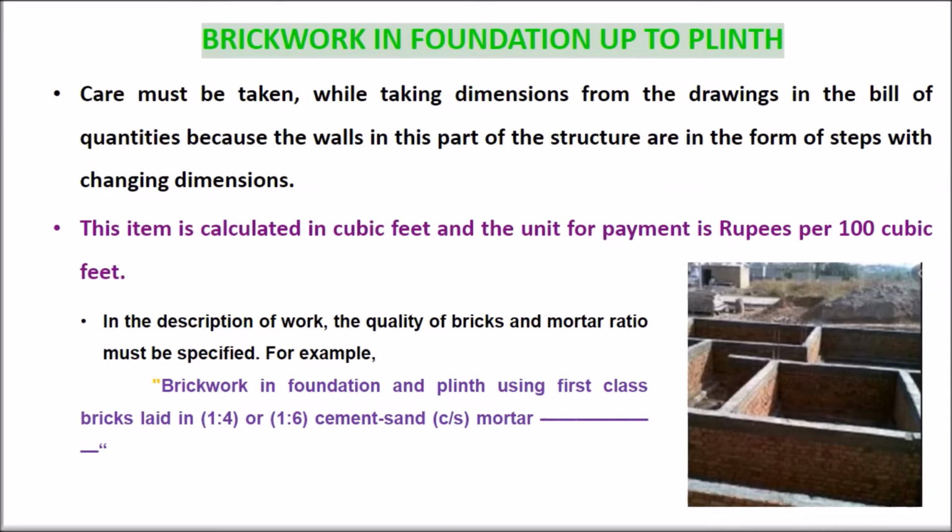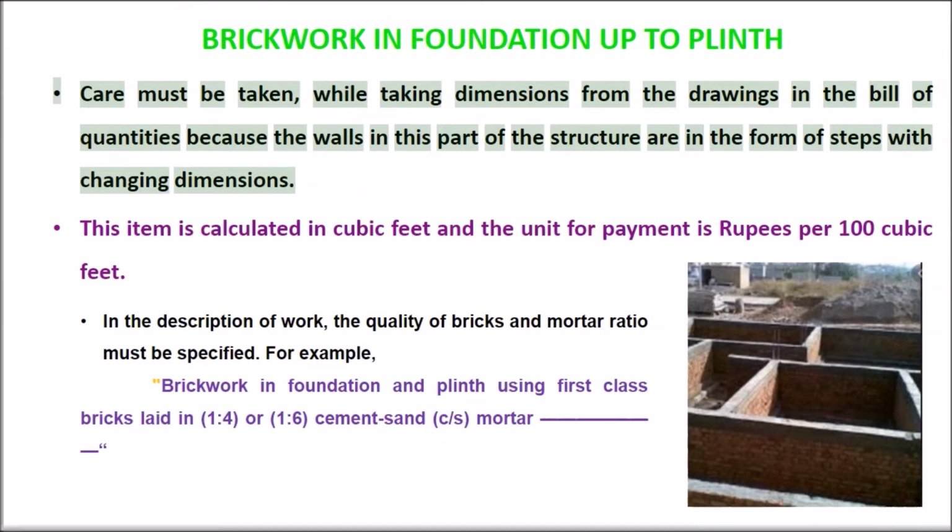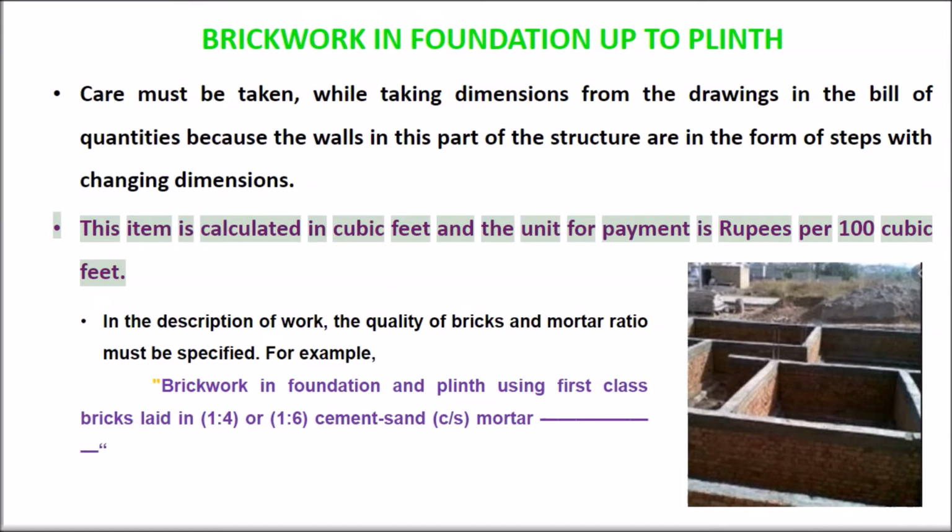Brickwork in foundation up to plinth. Care must be taken while taking dimensions from the drawings in the bill of quantities, because the walls in this part of the structure are in the form of steps with changing dimensions. This item is calculated in cubic feet and the unit for payment is rupees per 100 cubic feet.